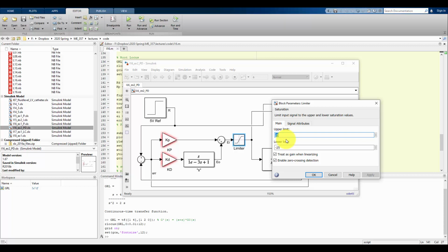A big drawback of using a derivative controller in a PD, or as we'll see a PID, or anything that involves a derivative, is that we're seeing the rate of change of error. Initially our error is 0 because we're at rest, and then we have an extremely high error because the output is 0 and the reference, like in this, is 5. The slope, or the rate change of the error, is extremely high. It's basically infinite initially, which means that the derivative part is going to be extremely high and approach infinity. It has this big, what's called a kick in our controller.